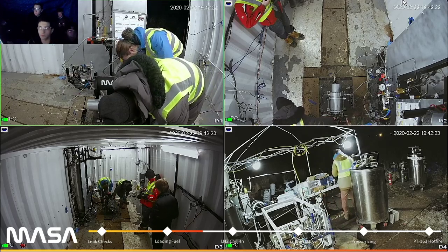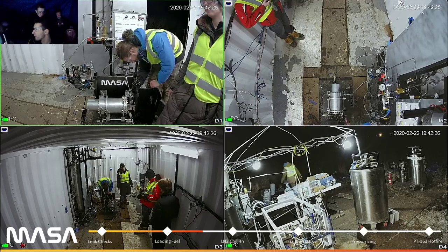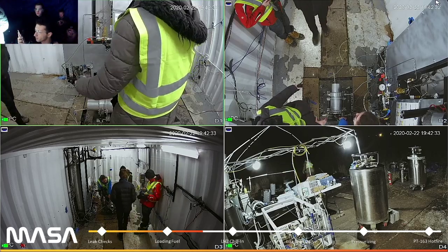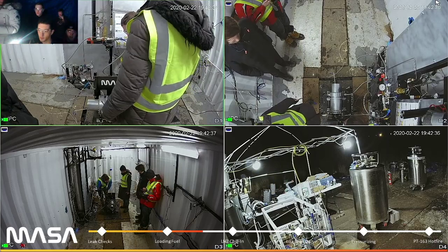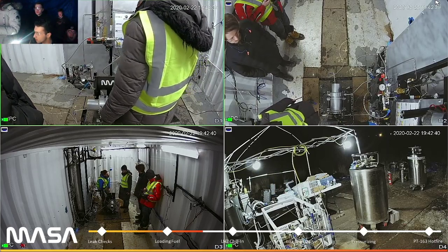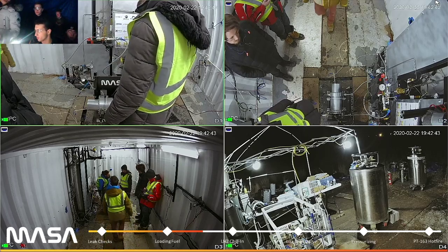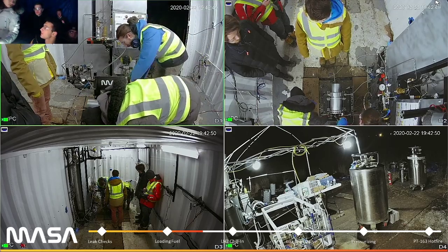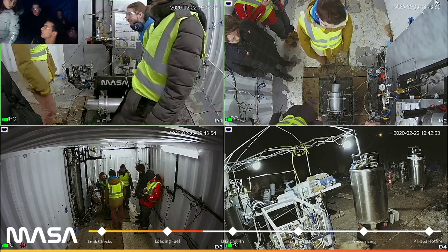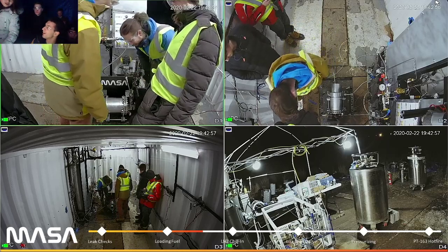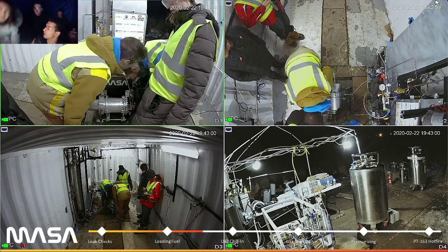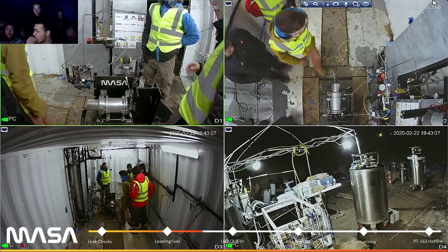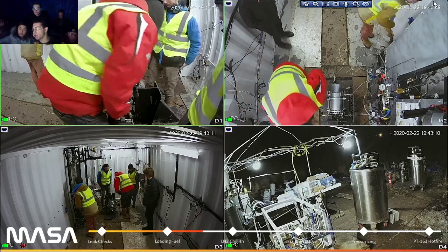But we have maybe between 15 and 30 pressure transducers, temperature sensors, and various measurements that we take on the tanks. Basically, every pressure vessel on the system has a pressure transducer on it, and multiple different points in the engine have pressure transducers on them. It's important to know what pressure we have in the entire system, since that's indicative of the performance. And we usually fill the tanks by looking at the pressures. All the data is being processed through our in-house built engine controller, which is currently running behind the bunker. So that's how we gather the data.